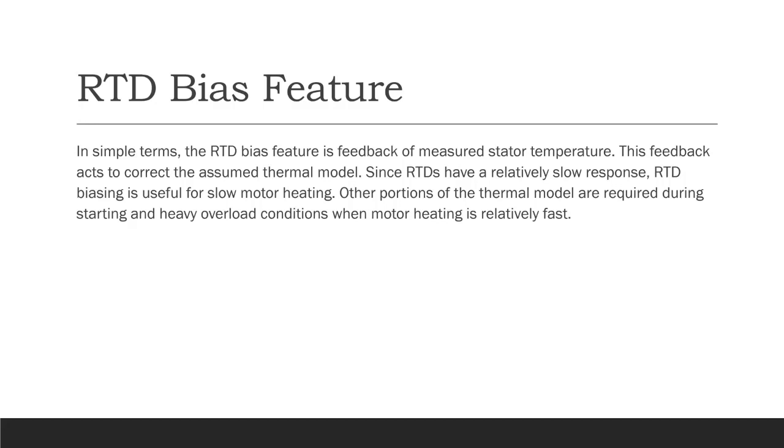This slide is right out of the manual, and I'm just going to let you guys read this, and I'm going to talk about it. And this tells us, and we need to emphasize, that a motor protection strategy involving RTDs only is not a viable strategy. The RTDs are a little bit slow to respond. Heat is somewhat slow to make it into the stator windings, especially when it originates in the rotor most of the time, especially in a high torque application. So the RTD biasing is not a motor protection strategy on its own. It is a strategy that goes along with the motor thermal model.